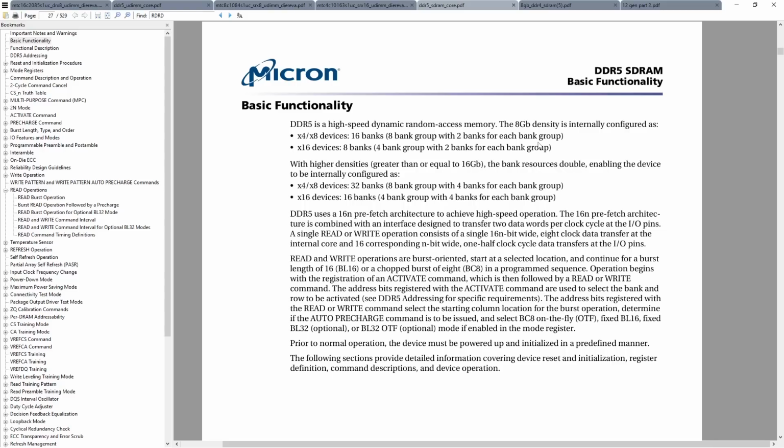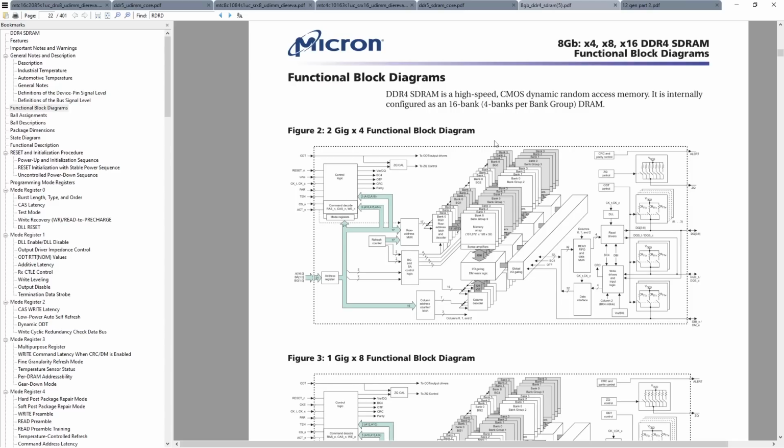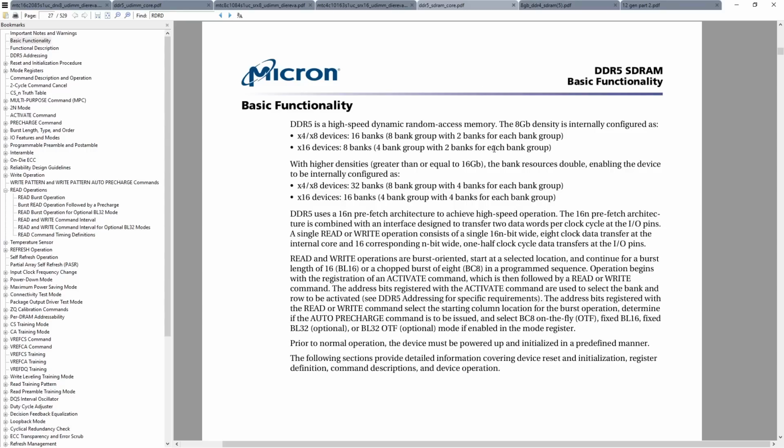And as far as I'm concerned with DDR5, there's really no reason to go from single rank to dual rank unless you need the extra memory capacity. With DDR4, of course, it's very different. You do actually want dual rank, but with DDR5, single rank might actually be just optimal for a while. So that's really cool, because one of the big benefits is that single rank DIMMs are always going to be cheaper, and actually the performance uplift is literally one of the main reasons why DDR5 has this new bank group configuration.